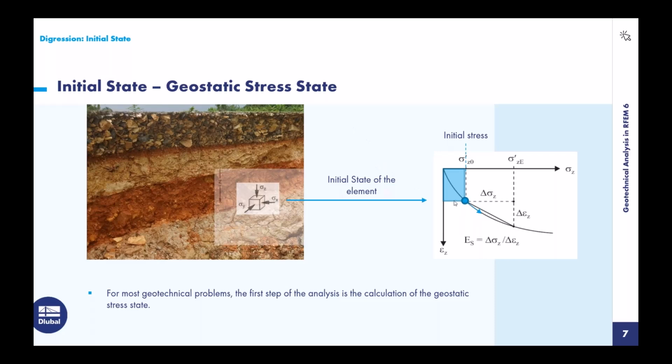So we reset this displacement to 0. So we have the stress state, we have the correct stiffness, and the deformation is set to 0 so that it starts to count the deformation from the further loading from our building. Okay, but we will see this in the program as well. That's enough for theoretical background. We now go to the program.